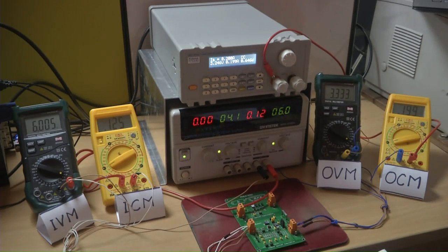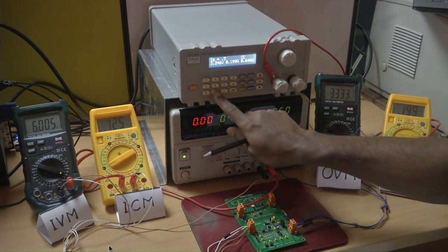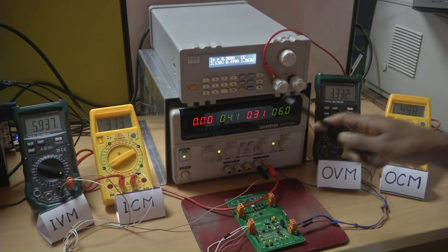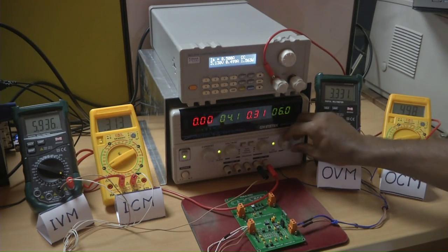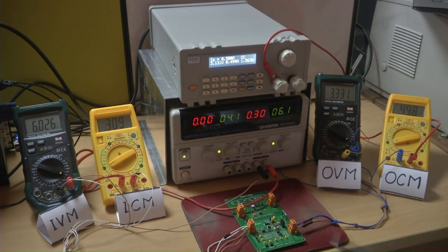As you can see, there is a very small difference that you see at the output. This electronic load is right now connected to the output of the buck converter. So this experiment was conducted over a range of load currents starting from 50 milliamperes to 200. What you see right now on your screen is the load current at 500 milliamperes. In fact, this experiment is conducted up to 1500 milliamperes, and we will take you directly there.